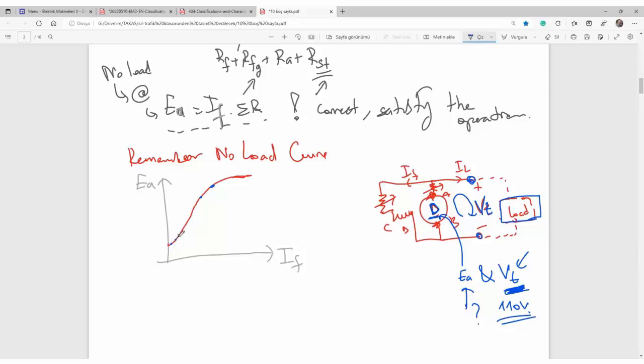For example, you've got a Ferrari, and you drive it at the speed of 40 or 50 kilometers per hour. If you have a Ferrari, sometimes you should drive it at 200 kilometers per hour, for example. The reasonable voltages would be here because you pay cost for the flux density. Flux density is equal to flux over cross-section area.